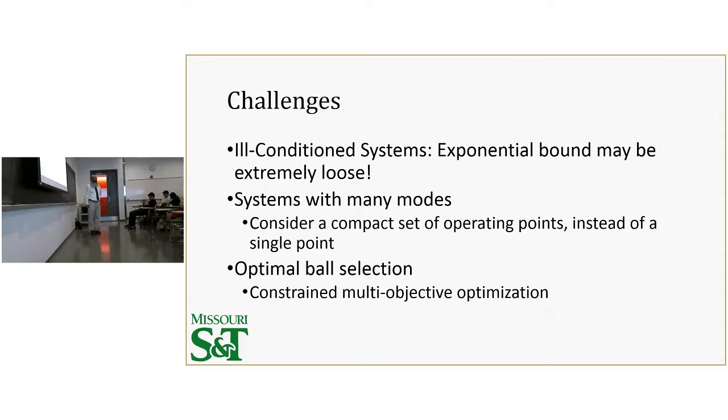All right. Basically, what you're doing, if I understand this correctly, is that if you wait long enough, you go inside these balls that, once you do the switching, will allow you to converge asymptotically to the equilibrium point of the new configuration. Right. How long you wait? Well, this is given by the decay rate on the Lyapunov function. That's right. That's right.